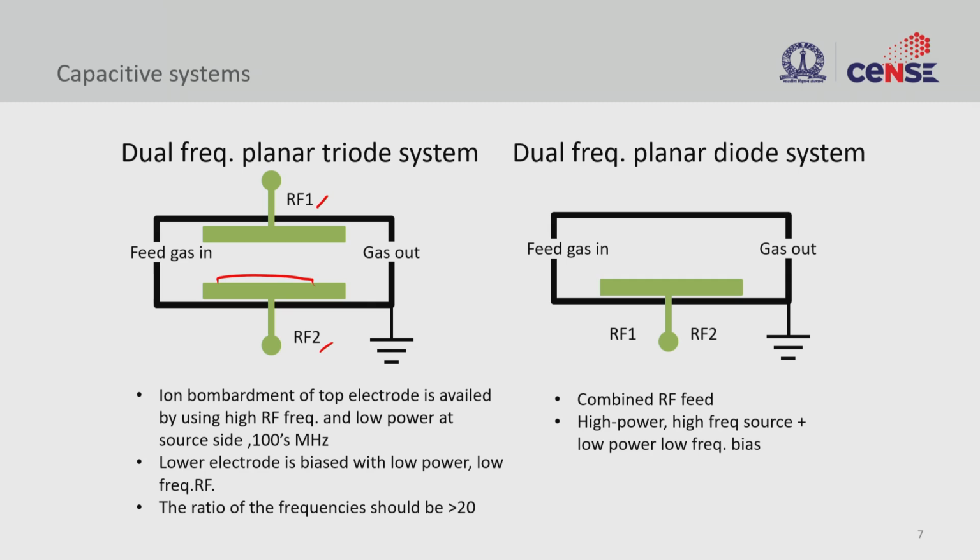But then instead of using two electrodes, people said, why don't we use two frequencies but just one electrode, right? But we can switch between these two. So you can switch between these two frequencies, high frequency and low frequency, so that we can feed electrons efficiently into the system, energize the plasma, at the same time reduce your ion bombardment.